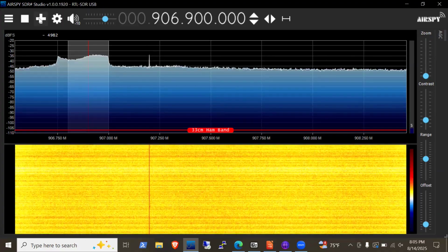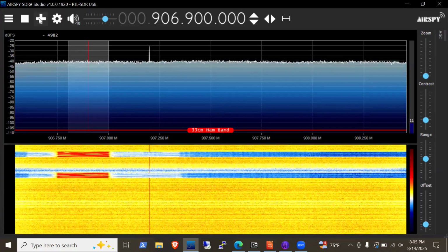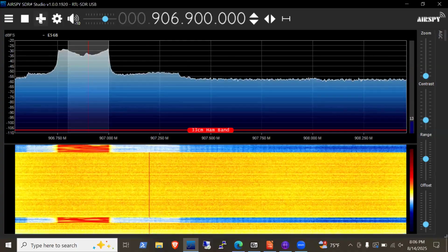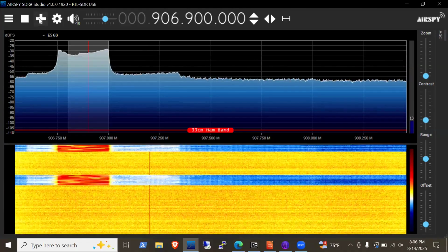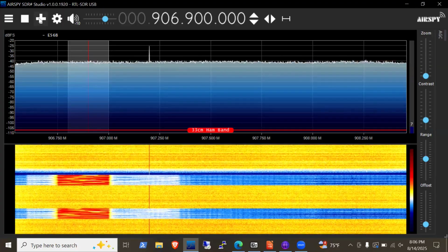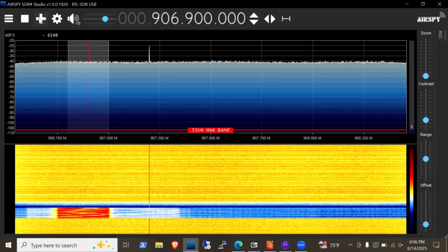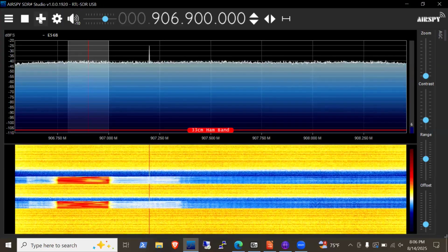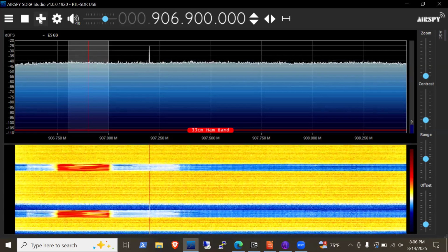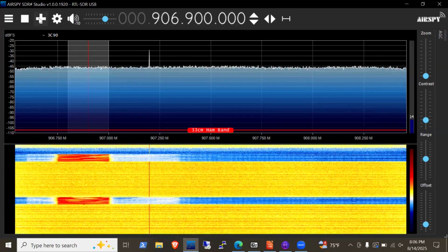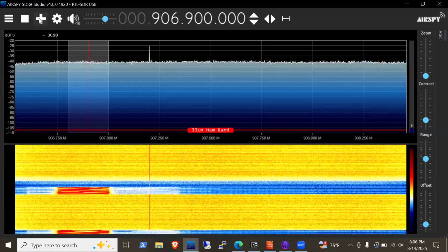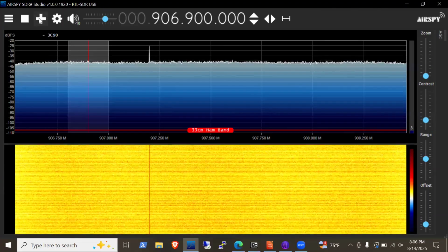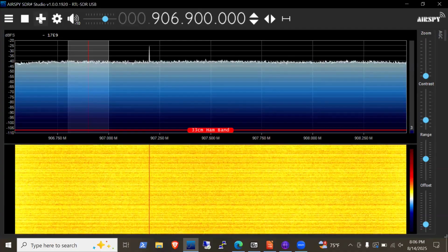Is there a Meshtastic plugin for the AirSpy? That's a great question. I bet there is. If not, then someone gets to write one. Yeah, that's a big packet. On paper, it can resolve these down to, I think, negative 122 dBm. We've seen it go down to probably negative 30, 40 and still get through, so it's pretty efficient. It's up there with FT8, using all that computing power to do math and pull things out.